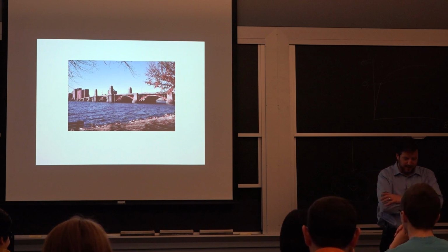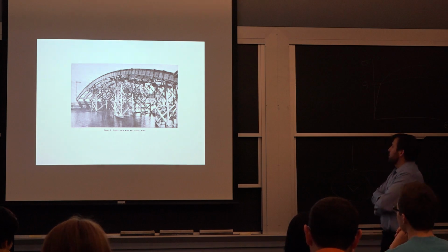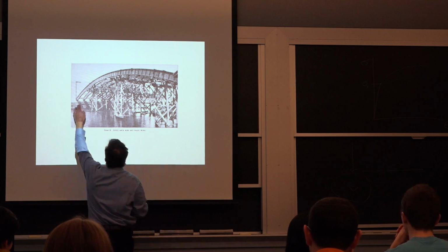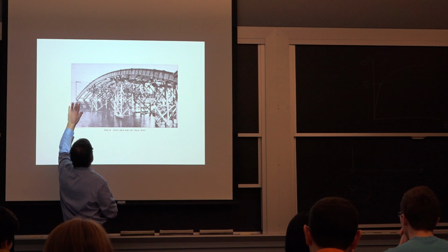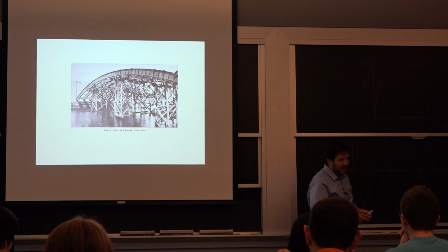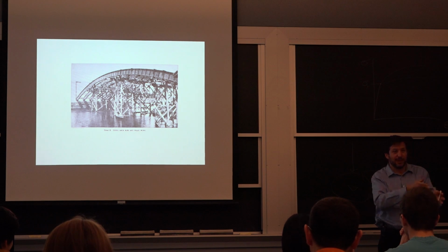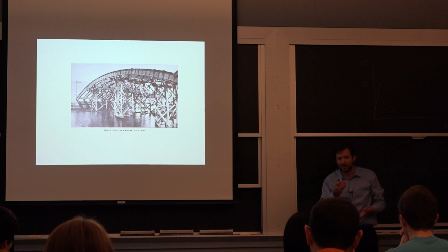So since it was fabricated, and that's just a view of how they're building the arches. I picked it out just because you can see this is the primary structure, the arches, and they connect to the different piers. So you have a lot of redundancy in that bridge. That's not a problem. The problem a little bit is you only have 4 members to hold a train, out of these arches, and if one of them goes, then it's no good.